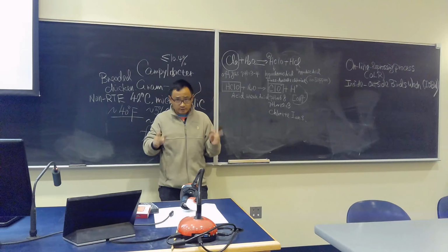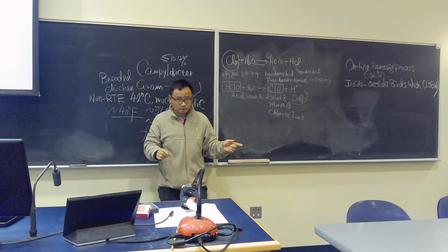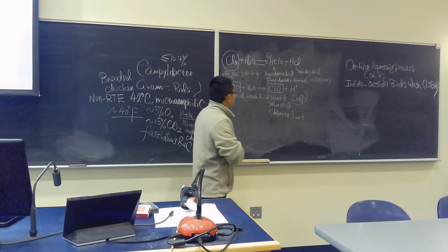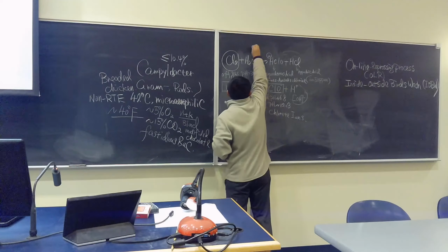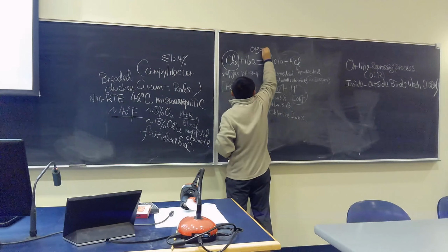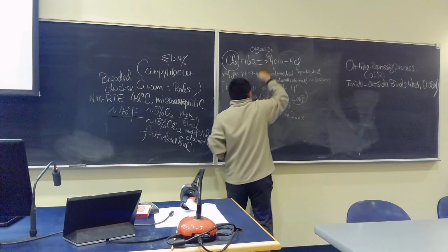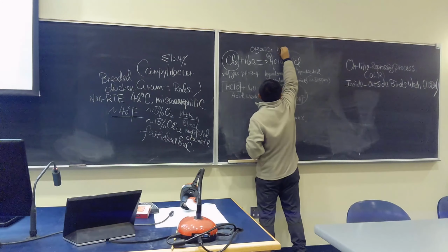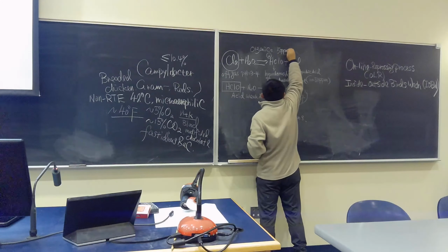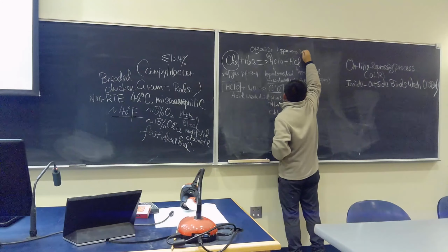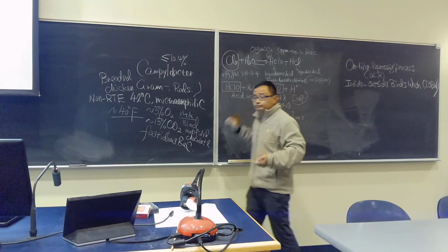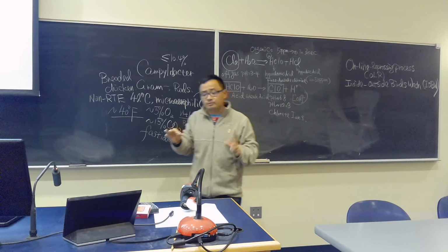This is some of the misconception that also happens in the plants. So you know the chlorine will react with organic matter. Organics, for example, could bring down 50 ppm to 0 in even 30 seconds. So what they do, they try to keep this at 50 parts per million.